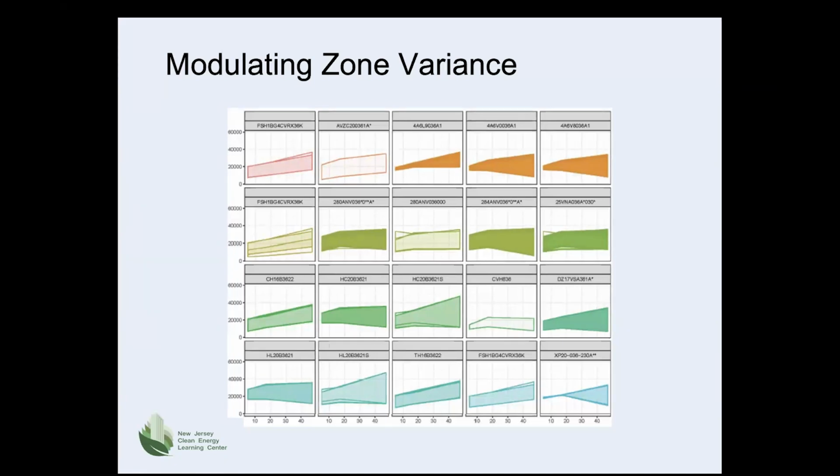Ideally, though, if you're in a colder climate, you probably are looking for increased capacity at lower temperatures. And examples of that would be the second one at the very bottom, as well as this middle graph here. This represents heat pumps that have high capacity at the higher temperatures, but also maintain a relatively high capacity on the lower end here at 5 degrees.